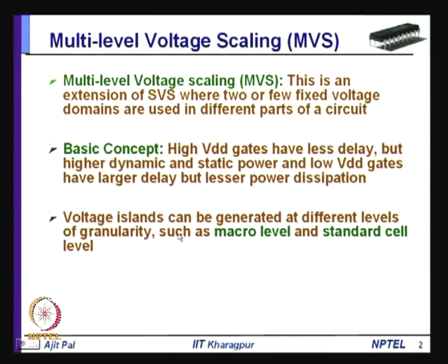We can create voltage islands at different levels of granularity, such as macro level and standard cell level. So, we shall have different voltage domains, and that can be done at different levels. It can be macro level, that means it can be a big circuit block like ALU, AD2 converter, transmitter, receiver, like that, or it can be at the standard cell level.